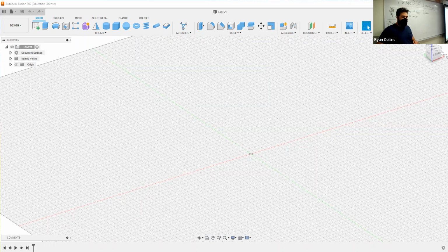Now, currently, it is blank. Down in the bottom left-hand corner, you'll see your standard play, snap left, snap forward, snap back, and then snap to end. As we do stuff on here, more icons will appear, and this line will grow. You can cycle through that, and you can also make changes like splicing actions inside and in between things. Or you can basically mute things, which is called suppress in Fusion.